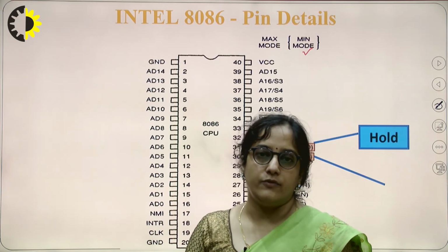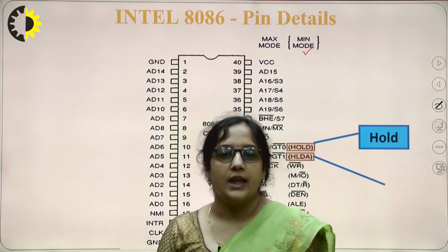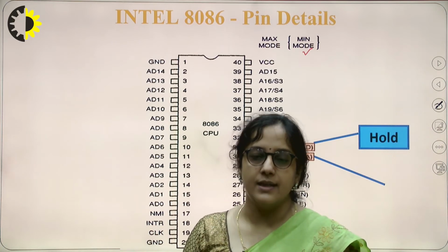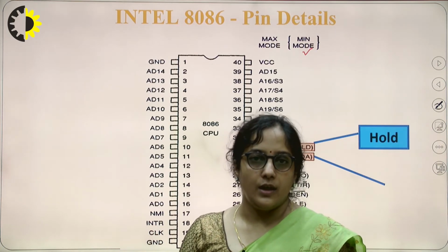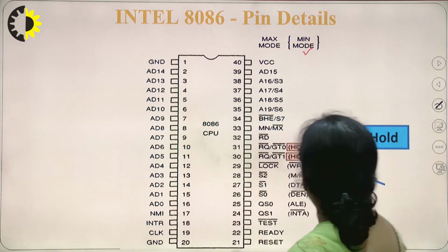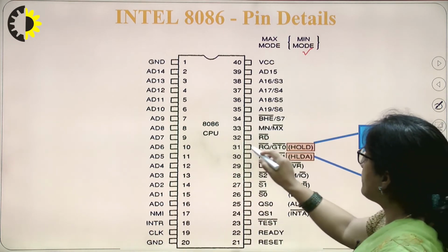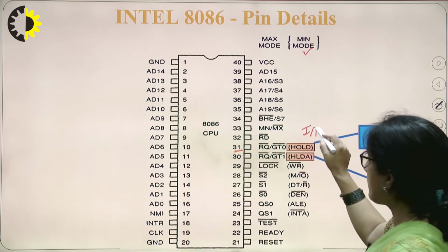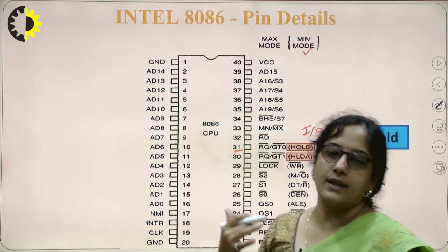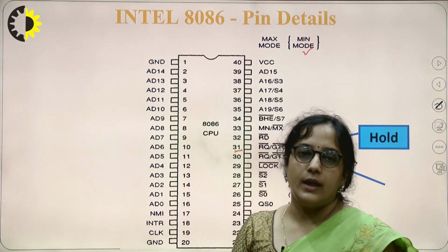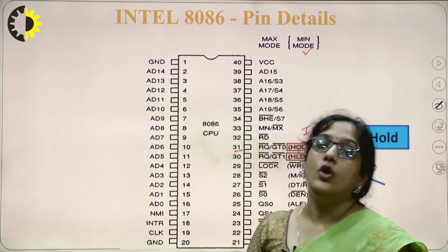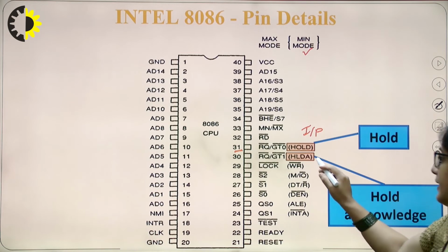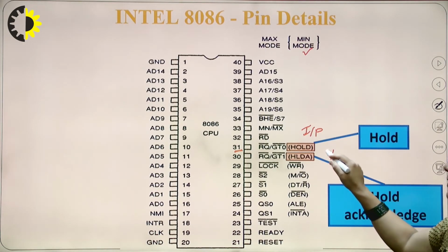communicate this operation. So, for that, DMA gets a request from any input output device, and when DMA gets a request, it will send a signal, that is the HOLD signal, to the microprocessor. So this pin number 31 is an input pin. It gets a HOLD signal, that is an interrupt signal, and when the microprocessor is ready to release the control of the bus, then it will generate this hold acknowledgement signal, HLDA, that is an output signal.